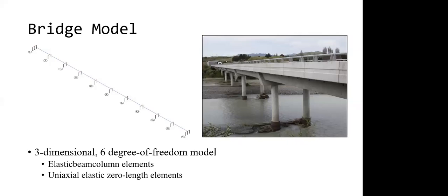When you were using rigid elements versus elastic elements with high E values for the diaphragm, what difference did you notice? You must have noticed changes in the periods or mode shapes. For my bridge, there wasn't a big difference.